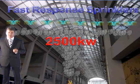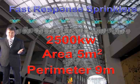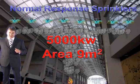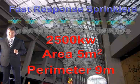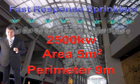And with fast response sprinklers, you'd assume a physical size of the fire is going to be 5 square metres, and it'll have a perimeter of 9 metres. Again, if it had been conventional normal response sprinklers, it would have been 3 by 3 metres with a perimeter of 12. These are fast response, 5 square metres and a perimeter of 9 metres. That's your design fire size. So we've moved that step, we know the design fire size.